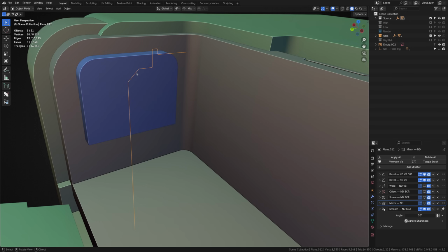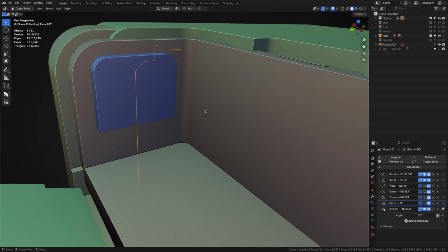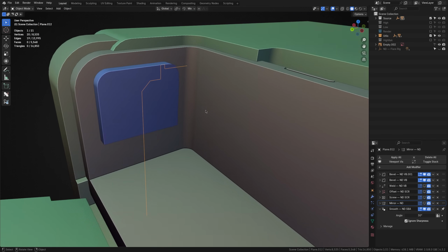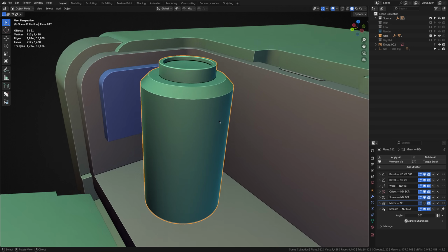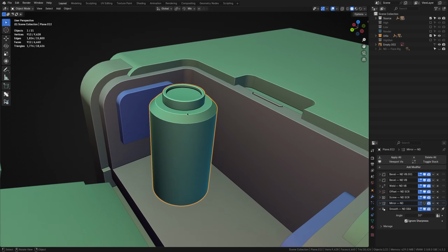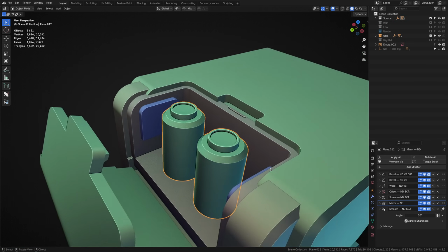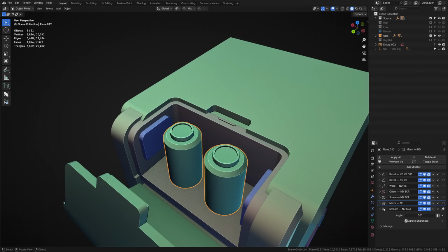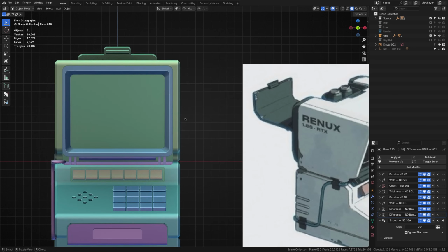This is a good tip for your own sketches. If you're drawing something out in a sketch and want a fillet or chamfer, add it as a vertex bevel. It'll save you a lot of time and give you more creative freedom. Okay, after that, I revolved the sketch around the z-axis, which created the final shape of the battery. Then, because there were two of them sitting side by side, I ran a mirror operation. And that's it. Let's look at one last example in the reference, which is a little more complicated.